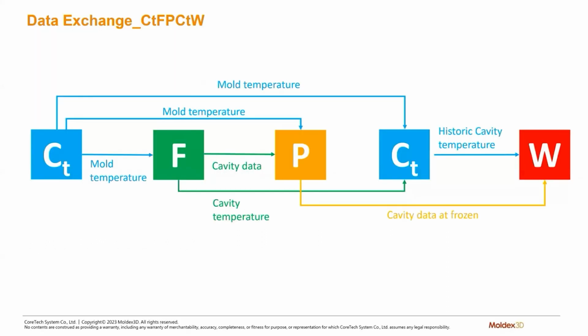This one shows how the data is exchanged between each solver. Usually we recommend running the simulation with a full analysis, so it will have a cooling, then flow, pack, cooling, and warpage. The first cooling will calculate the thermal analysis for the whole cycle time.